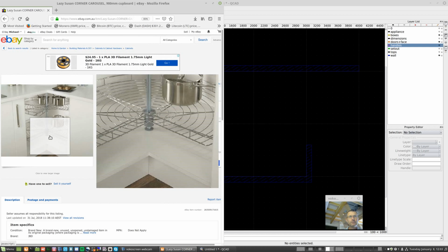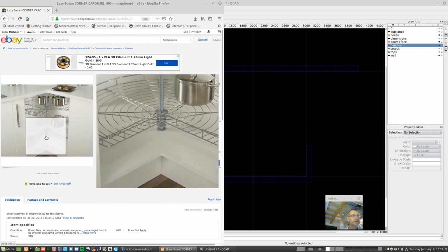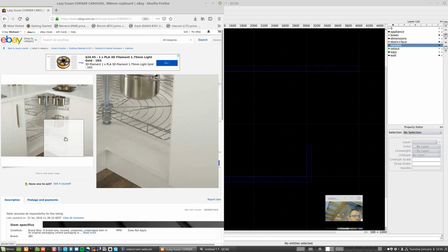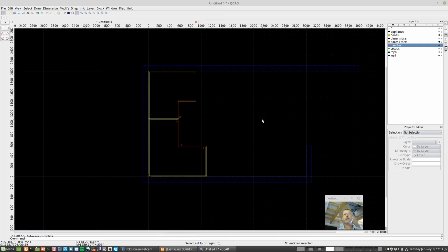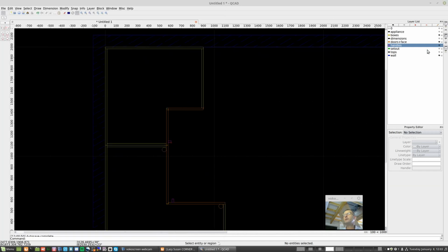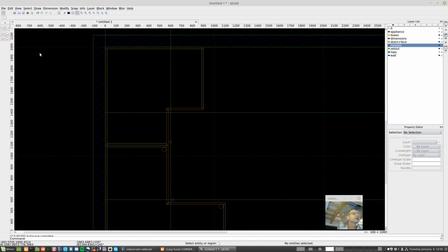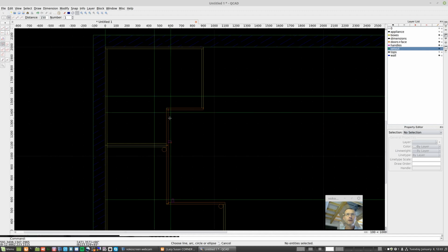The pivot point is well back, right? And that is a common problem. So let's just do that on the drawing. Now, it's not going to give us the specifics, but you can see visually that's about 150mm back both ways. So let's just go back to our drawing here. So 150mm back both ways. Let's draw a parallel. That guy. So that's the pivot point, about 150mm back both ways. I want that on the set out layer, please. Now it has to be that far back so as to give operating clearance for rotation.